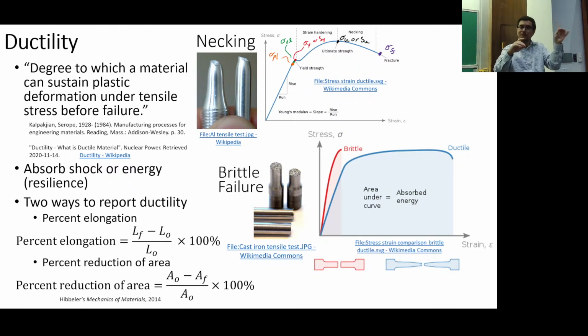So let's do an experiment. If I do this now, what kind of surface should I get? This is a brittle material. I have normal stresses involved with this bending procedure, and that's pretty good, okay? All right, so you see that this is now kind of jagged, like we were expecting, and you can pass it around as well.